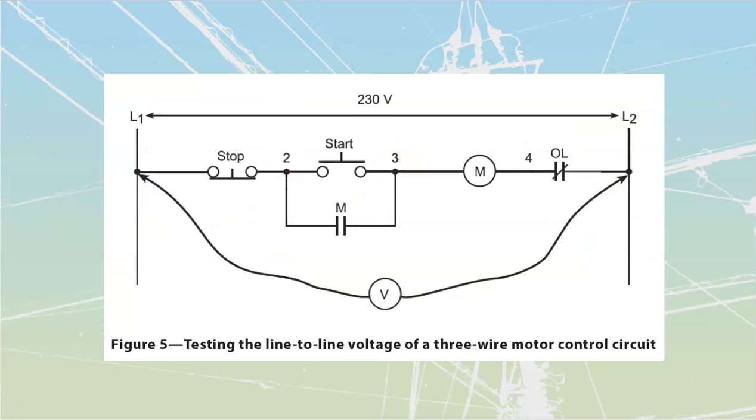Going on into my control circuit analysis, control circuits are going to be analyzed in a lot of the same way. We're going to work with where we know that we have got power. And I'm just going to draw right now two lines that are going to go through here. First of all, you should remember that we don't drop volts until current flows. Across an open switch, we always have got full line voltage.